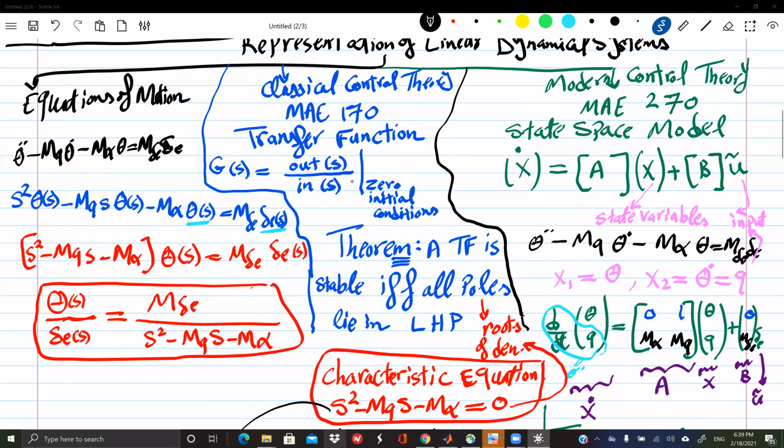So it's an 8th or 9th order system, and I want to design it to achieve the following performance: settling time ½ second, and 0 overshoot. First of all, this is a crazy desired response, and it's not physical, and a huge airplane like a 747 will never be able to do it. But aside from the practicality, can you at least theoretically design a control that does that? Well, frankly speaking, I can't in the classical control theory. Using a PID or any of the controllers that we learn in the classical control theory, I cannot guarantee that I will achieve this performance, theoretically at least.